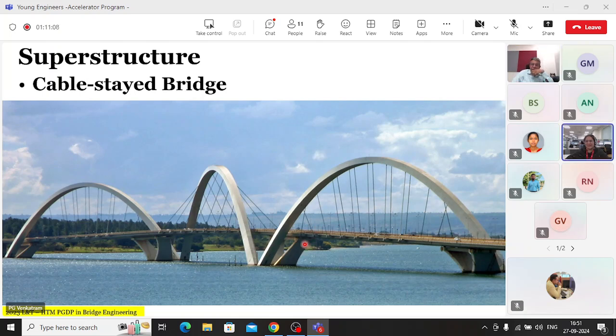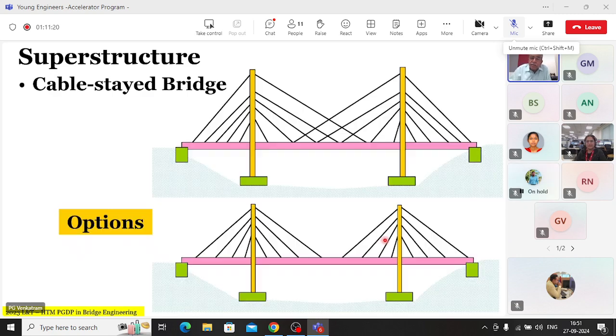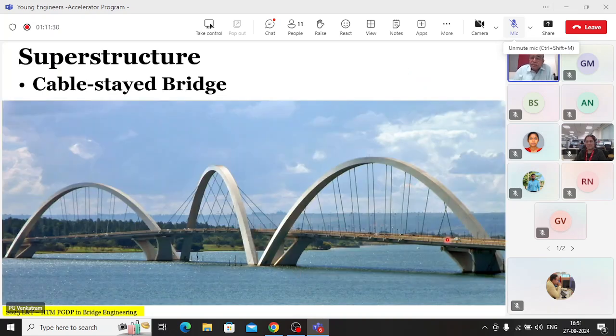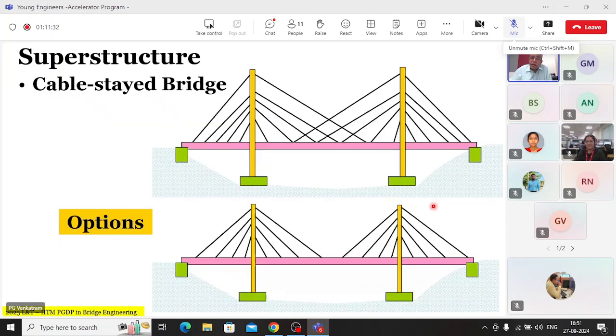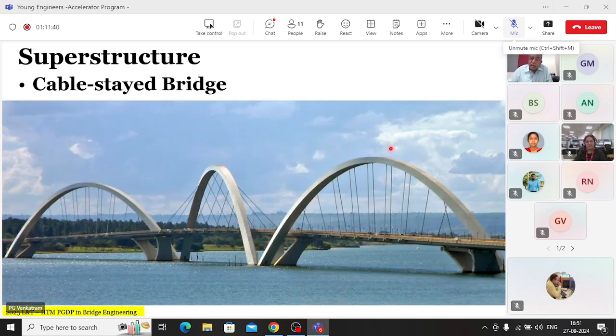Suspension cables are not there. In a suspension bridge, the main load carrying member is in tension. Here, the main load carrying member is in compression. That's exactly similar to this. The difference between this and the cable stayed is that the pylon is vertical, and in this, the pylon is an arch. Both of them carry compression. In one, the load is transferred to direct axial compression on a pylon, and in this case, the compression flows through the arch. That's all the difference is.